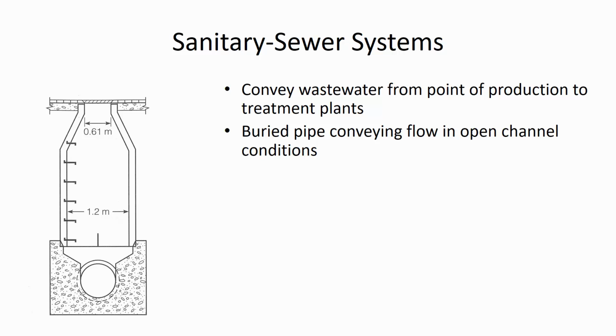So the sanitary sewers and also storm sewers work with the same idea, that we're trying to convey wastewater towards some point of treatment or point of disposal. And generally it occurs in buried pipes that are flowing with open channel conditions, which means that even though it's a pipe, we're going to be using Manning's equation.